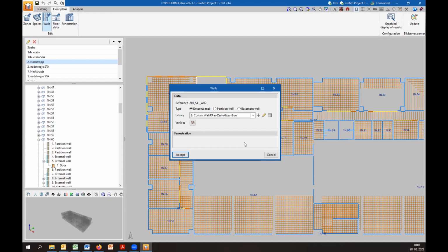So if we don't want to start modifying the definition of all the partitions, we have two options. First option, going to Revit and checking the function of the internal layer of this sandwich panel or whatever, in order to check why it is considering it as an internal wall. Then, if it's defined correctly, going to the OpenBIM analytical model.